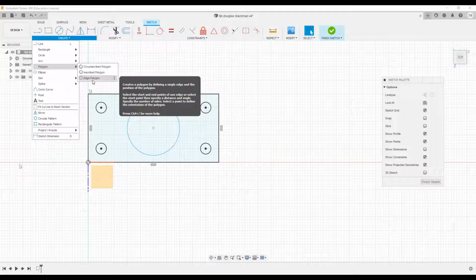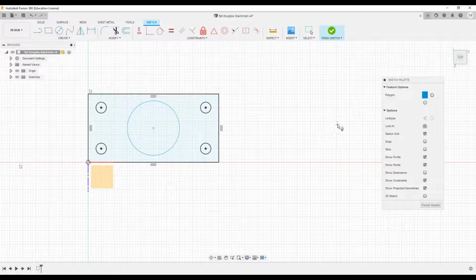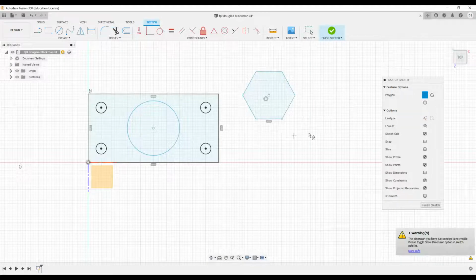This is the polygon tool, and this allows you to draw an any-sided shape that you want. So you can see, I could say, okay, I want the side of my shape to be 10 millimeters long. I always draw it slightly wonky, so I can press Tab and 0 to make it nice and straight. And then we can decide how many sides we want that shape to have. The standard is set to 6, but we can set it to 3, 4, 5, 6, 7, etc.